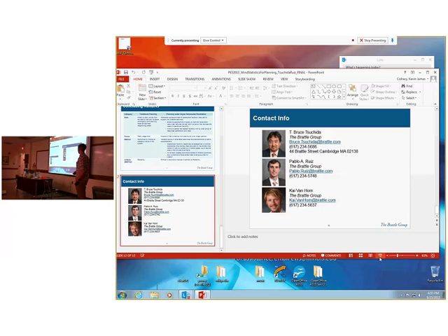I don't think this presentation puts forth a specific approach. The purpose of this presentation was to facilitate a discussion about how we do transmission planning and how we can do it better in the face of integrating renewables. Yes, there are metrics we can use. We can assess the average or adjusted production costs in the system under different scenarios to get at the value of flexibility. If you put a new line in the system, you can see how much the production costs were reduced by adding that line, and that's one component of the benefits. Or increased, even. That's also true.